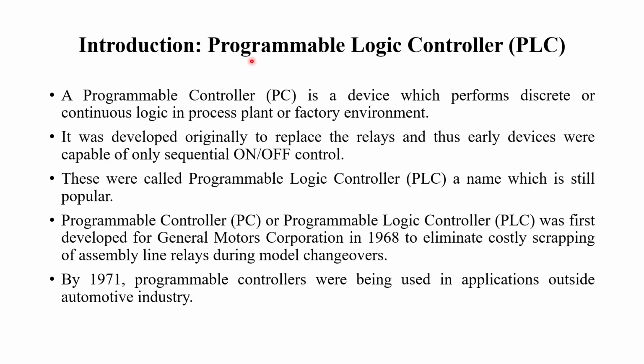So coming to the introduction to programmable logic controller. What is a programmable logic controller? It is actually a programmable controller. A programmable controller is a device which performs discrete or continuous logic in a process plant or factory environment. The main objective of developing a PLC is to replace the relay, which is capable of performing sequential on-off control.